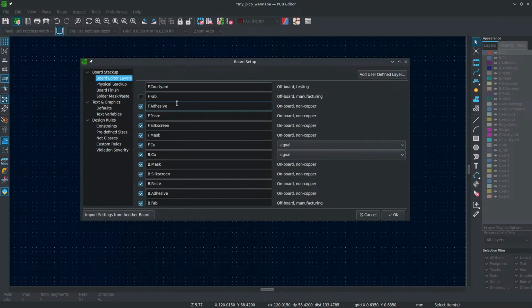Then we have adhesive. In manufacturing circuit boards, we think we solder a component down to a board and that holds it there mechanically. But a lot of times components, particularly larger components, will additionally need glue to hold them down. Capacitors, for example, will have glue to provide additional mechanical strength. If your board is vibrating and you have an electrolytic capacitor there, it'll move a little bit and eventually break a leg or something.